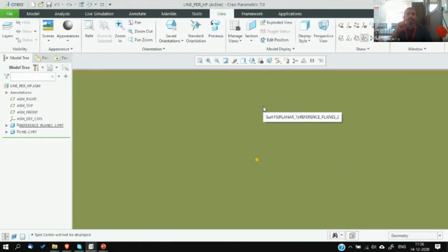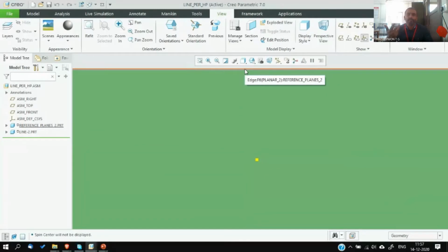Since the line constitutes a succession of points, the top view of this particular line will be a point. And the distance of this point from the XY line, we don't know. It depends on the question. So the distance of that particular line from VP will be equal to the distance of this particular point in top view from the XY line. So let's see how it is being done.